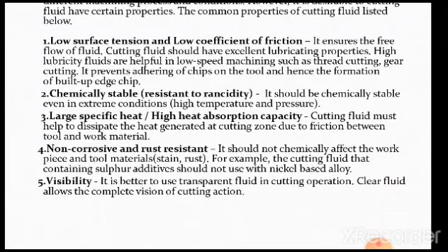The next, second one, is chemically stable. This is one of the required properties of any cutting fluid. It should not start boiling by itself, or start giving a bad odor, or even start giving off any fumes, because it is sent into the cutting zone itself.